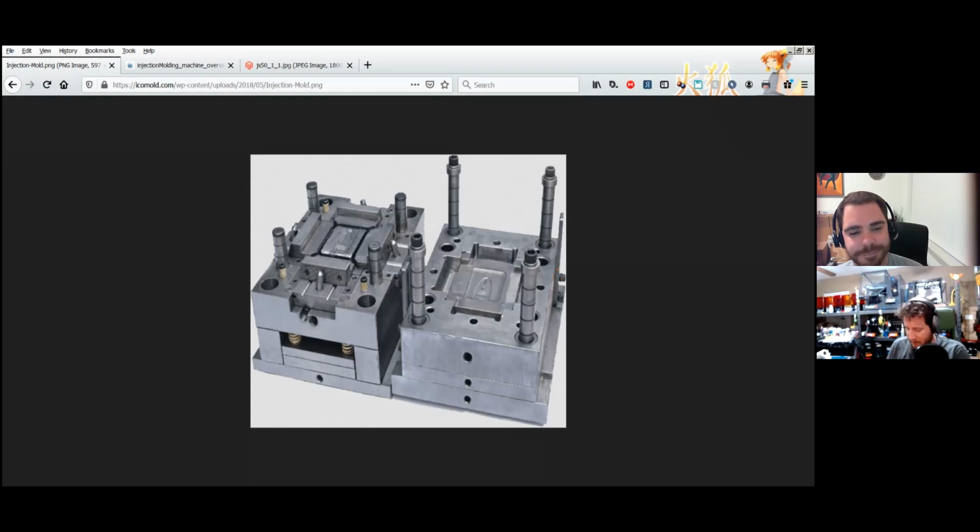So when they're together, it's hard to do it. I'm trying to put them together. They're actually stuck. And because this is RTV, so it's room temperature vulcanizing rubber, if anyone didn't know what RTV stands for, it fits on just like that. And to get it off, you just peel the silicone off, which is totally fine for this particular use case scenario, where they take like 8 hours to make because it has to vulcanize. That's totally fine to peel it off.